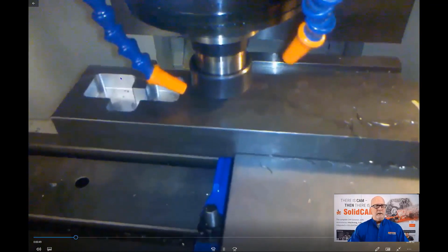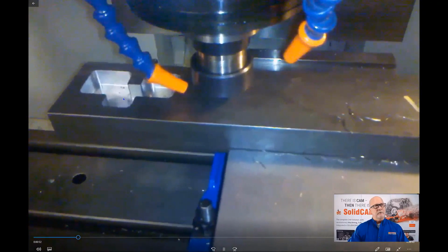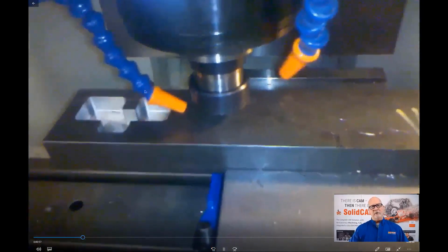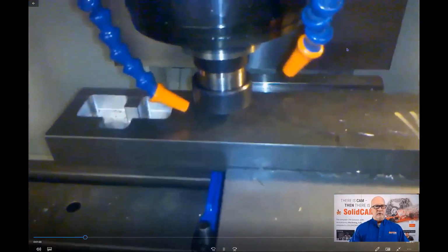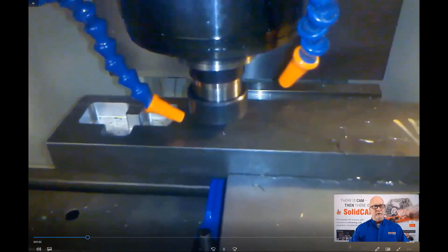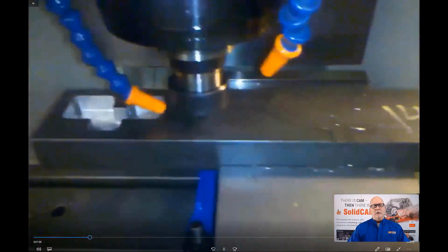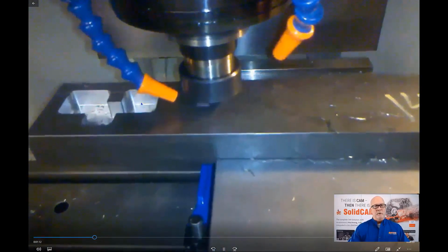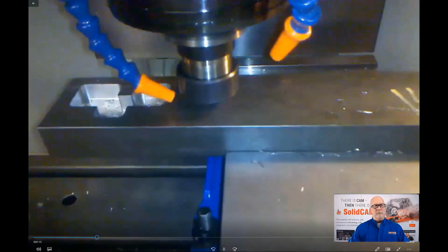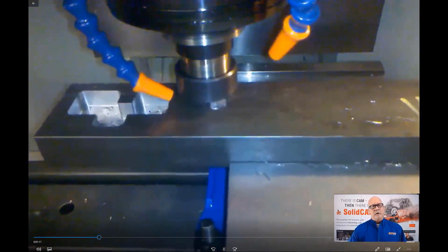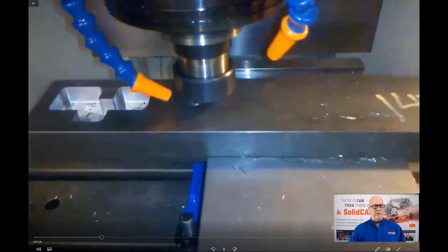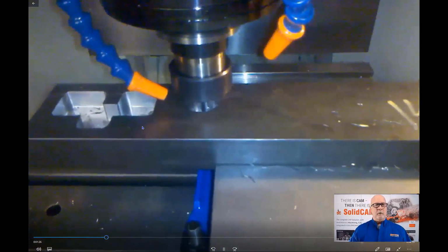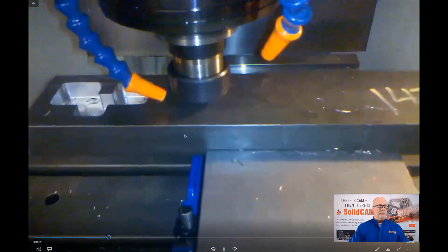So this pocket, he had to cut at 50 thousandths depths of cut. At 2,200 RPM, and 18 inches a minute was the fastest he could go without creating so much stress on the column that it vibrated things so bad that it was just chipping up the tool, just tearing it up. And so this pocket took him 2 hours and 26 minutes cycle time to cut it. And by the time he got to the bottom, he'd pretty much destroyed the bottom 50 thousandths of that tool. And he had to put a new tool in here to finish the walls. And then he would use that new tool to start the next pocket. So he was basically getting one pocket per tool. So his tooling cost was fairly big.